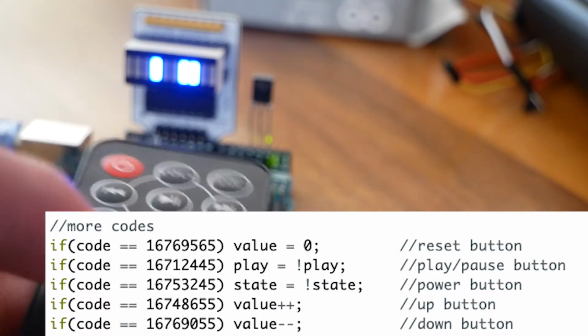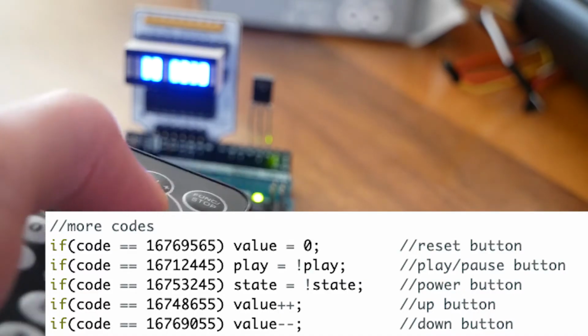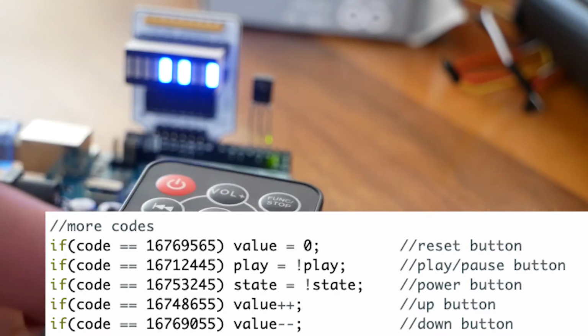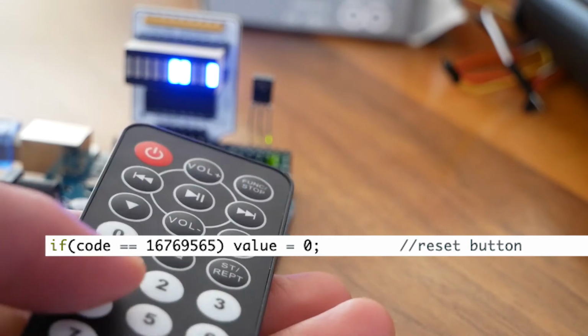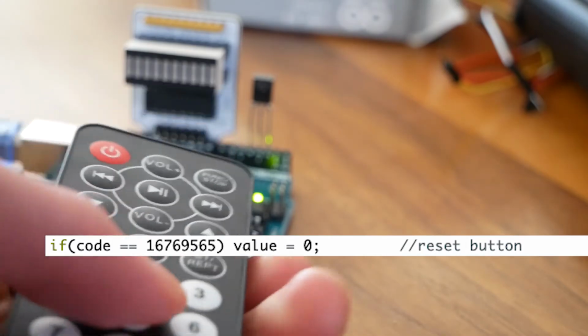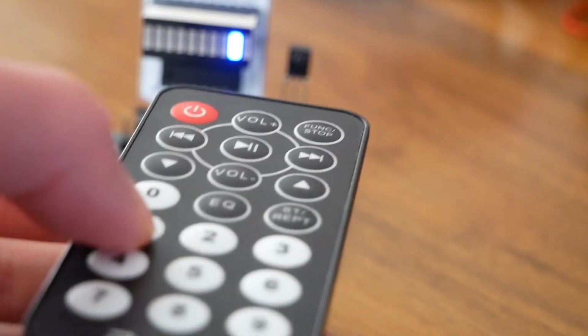If statements then compare the received IR code to the predetermined IR code, and if they match, the value is altered in some manner. For example, if the stop button is pressed, the ATmega will match that IR code with the stop button IR code, and the value will reset to 0. The same goes for turning on and off individual bits.